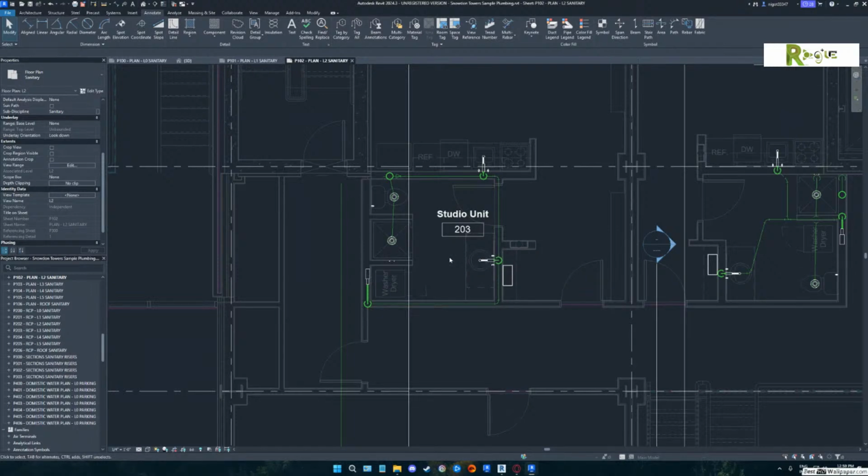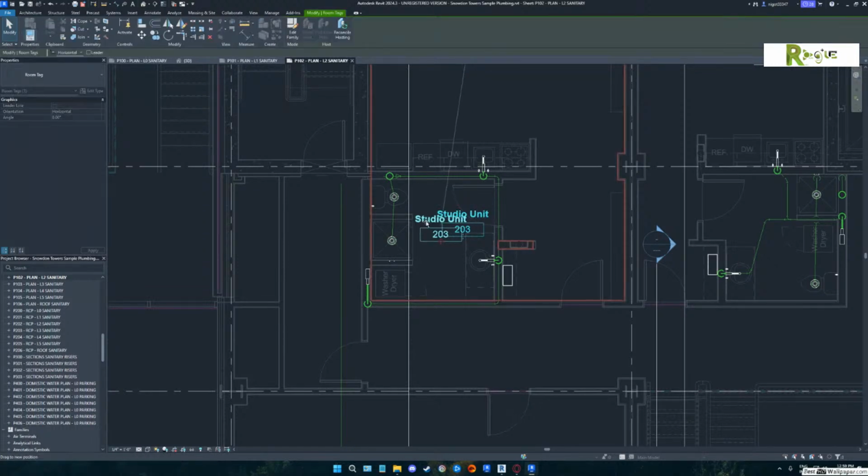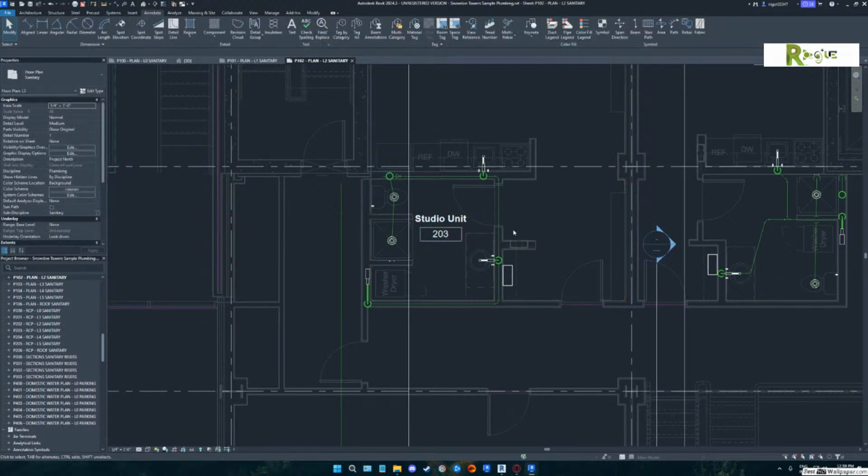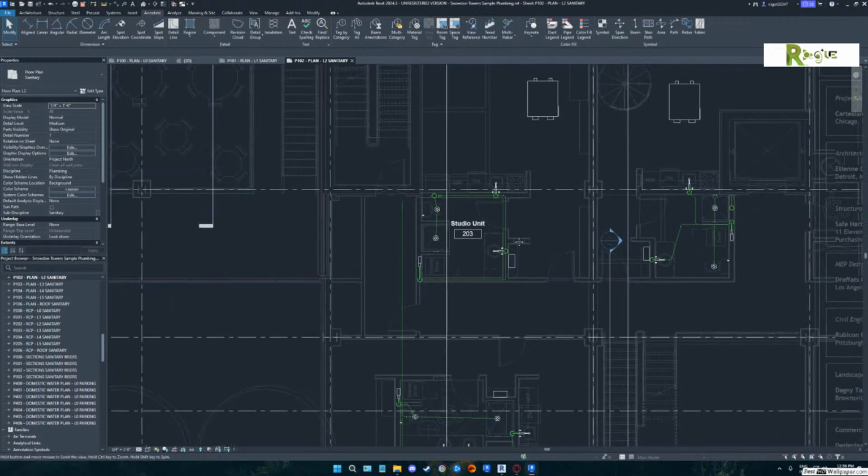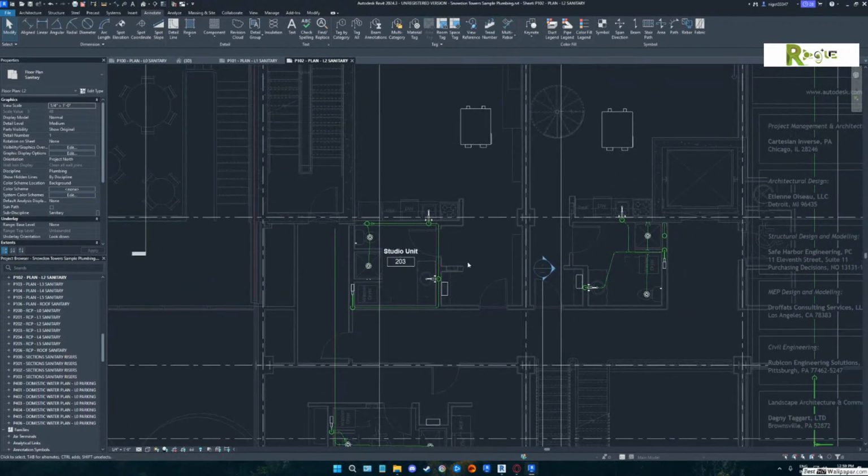So in other words, this isn't something that's going to be hard and fast. This is going to be something that you're going to need to do for each one of the sets of drawings, because remember what I told you going back to drafting 101, that tag should not sit on any objects. Right? You try to find open space for them. Always. Tag the other rooms.